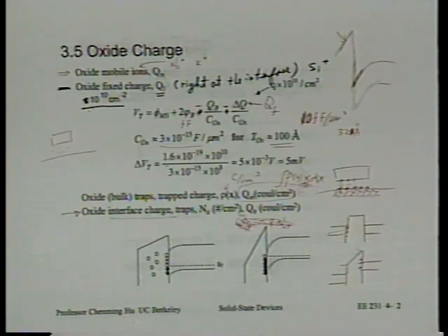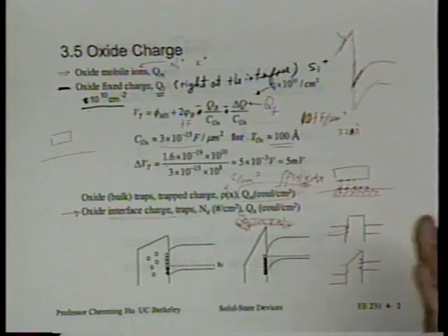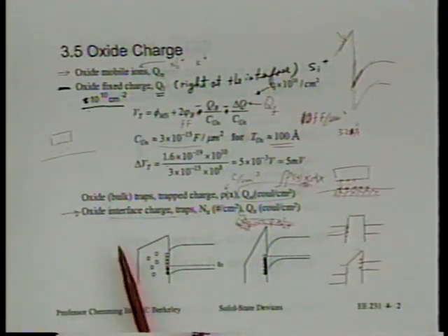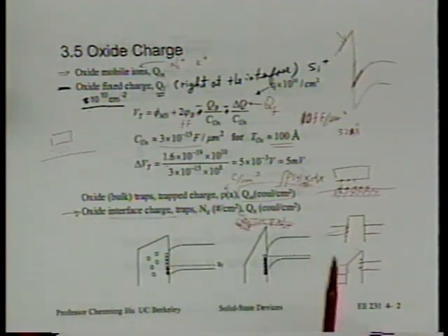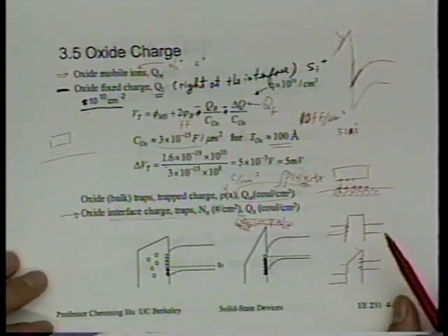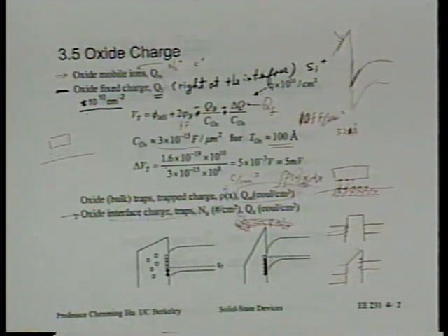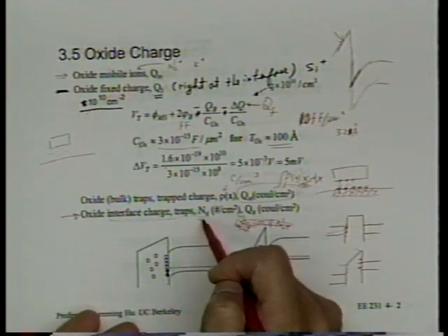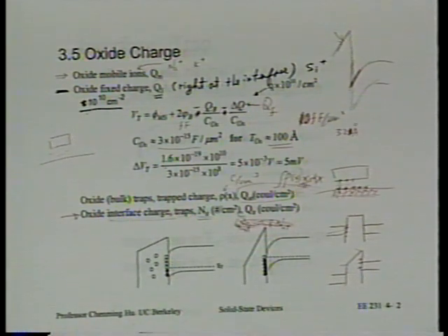I mentioned it here just so that you can see there are different things that can cause the bond to be broken and interface trap to be generated. It's for this reason this is particularly troublesome, because even if a material appears to be good, you can do whatever you want to test it, looks very good, but later on this device doesn't look good, the circuit doesn't work, and that potentially is a problem. So interface trap is something we particularly want to pay attention to, all right? And not only that, it also varies in real time. That's the interface trap density can be generated by stress.